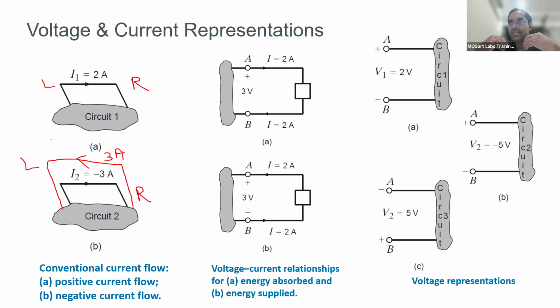Okay, so whether you are delivering the power, again the same thing here. You can use a convention to say if I'm delivering the power, then it is a positive quantity. If I'm absorbing the power, then it's a negative quantity, right? But in reality, keep in mind, fundamentally, all these quantities are real positive quantities only. You use a minus sign to indicate an opposite direction or indicate a different property.